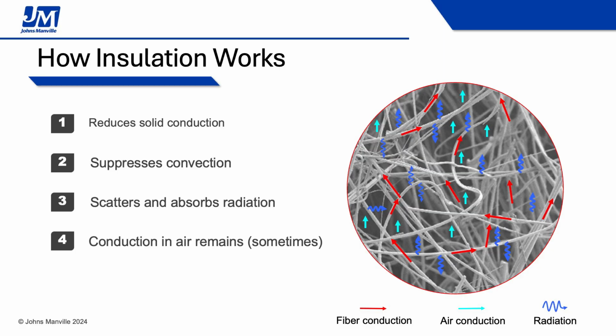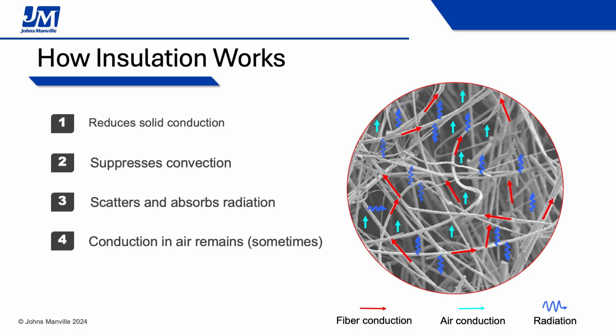One of the things that drives R value at the same thickness would be density, right? The more fibers that we can pack into a given volume, the better those fibers help scatter radiation. Instead of 2/3 radiation, 1/4 convection, 10% conduction, when we put insulation in the way, it becomes like 75% conduction through just the air and 25% radiation and no more convection.